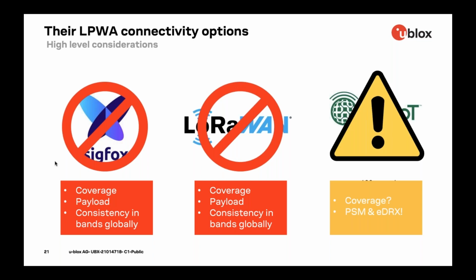So if you know that you're doing a water metering solution that's going to run in a particular city, then it's obviously quite easy for you to know the network that you'll be on and do those calculations and have that reliable information. But for everyone else, it's a bit of a minefield and can be quite complex to work out. So you may well find that the power savings that you think you can gain from these low power networks are actually not that significant, and maybe the 2G and Cat1 LTE networks will give you similar results, especially when combined with a carefully considered protocol as well.